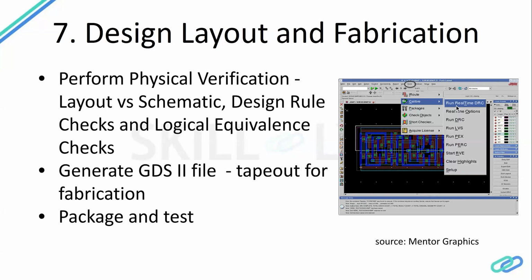Again, apart from these, there are certain stages which happen in parallel, like design for testing, which is designing the logic or the hardware which is focused on the testing of the design or the hardware. You need some kind of access to the IC once the IC is ready, and design for test, or design focused on the debugging part, will give you that access, and you will know what is happening exactly inside the design when you go for DFT.